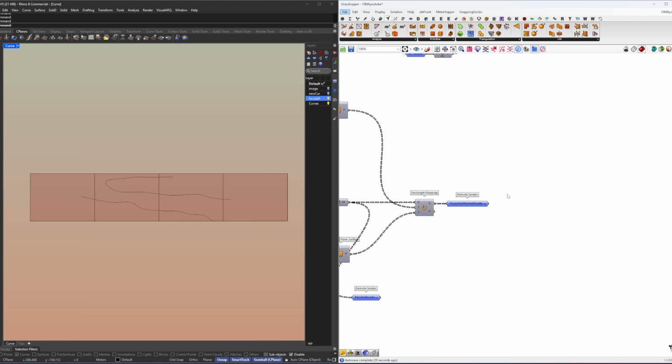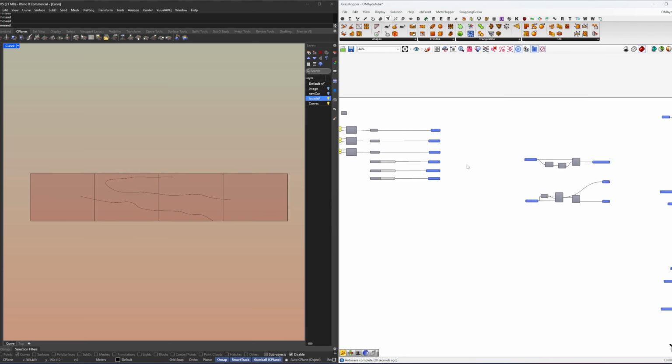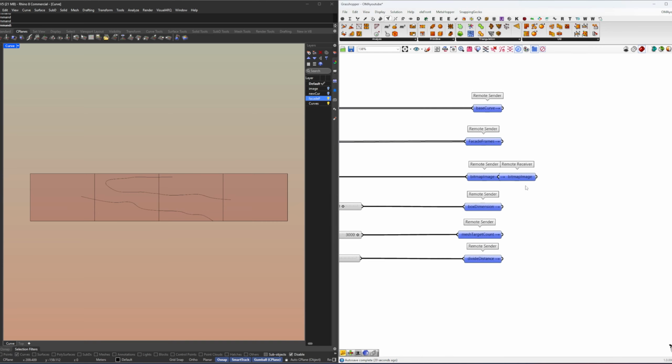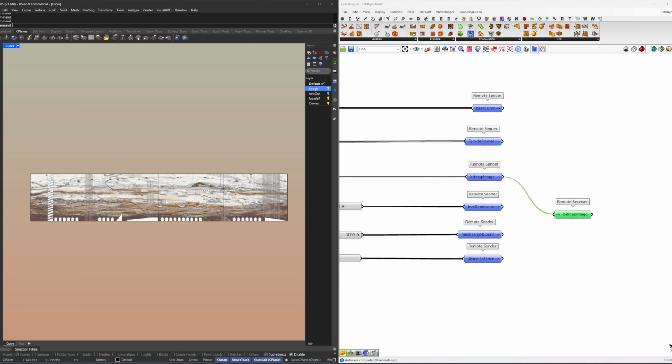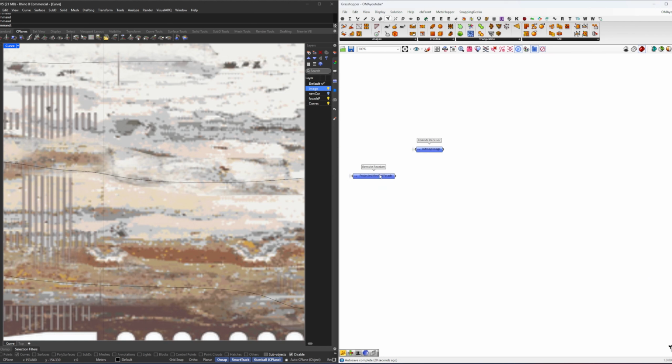First thing we're gonna do is Ctrl M, because I don't want to see the preview mesh at all times. We need the projected mesh facade, and we also need the bitmap image, which is this image. Those two we need at the moment. So let's first flatten this, then mesh explode and again flatten it.